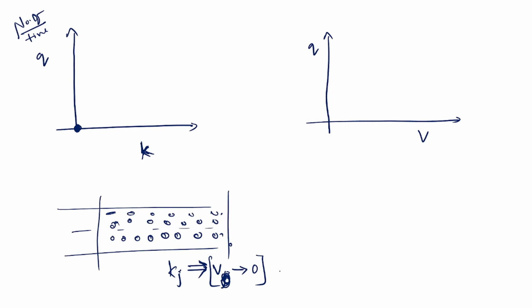When the speed tends to 0, then only jam density happens. When V tends to 0, flow will not happen. Flow means crossing a particular point in a time, so Q also will tend to 0. That's how when K is Kj, Q is also 0.